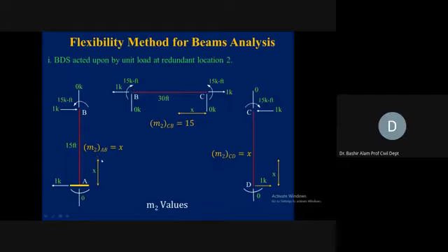So joint B. And similarly now here, we need to transfer this to joint A now. So 0, 0 horizontal, it was rightward, this is leftward, this is counterclockwise. And here now, why 0? Because 1 times 15 is 15 clockwise and 15 counterclockwise. So 15 minus 15 is coming 0. So that is why here we are showing this 0.